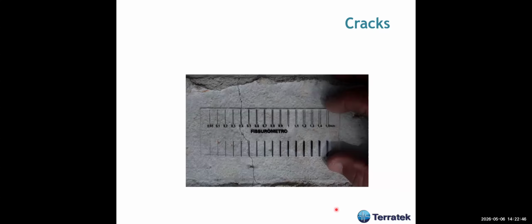And then usually you measure with a device like that, with a template like that, the width of the crack. And if it's over 1 millimeter, that's the kind of criterion that I use. Over 1 millimeter, I refuse the pile.